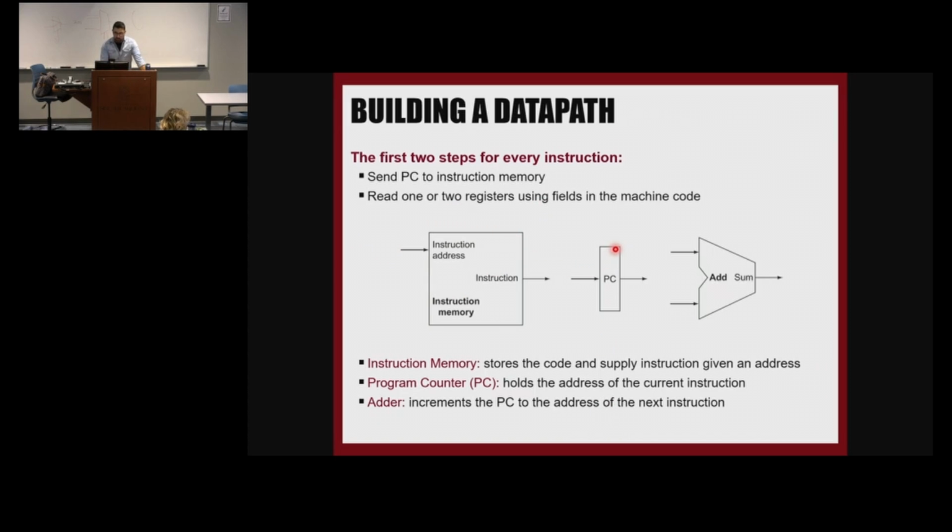We need a program counter register, we need an adder, because right there in the very first step that we fetch the instruction, we also increment PC by 4 because we want to point to the next instruction. That happens during fetching the first instruction. Okay. So this is different from ALU. It's just an adder that keeps adding the PC with 4. And then we have the instruction memory, which is where machine codes are stored.